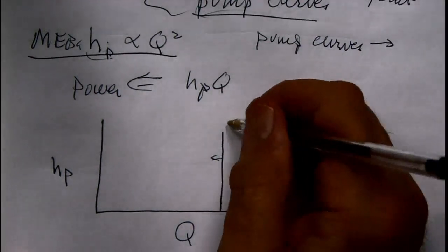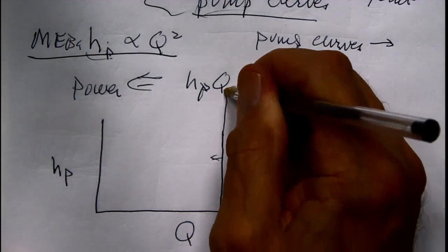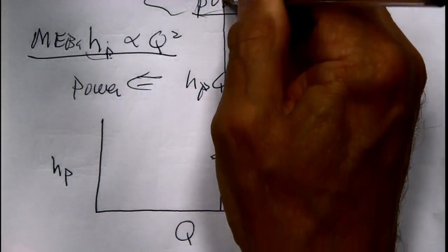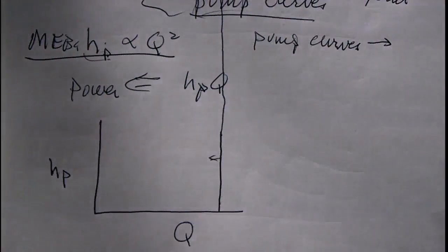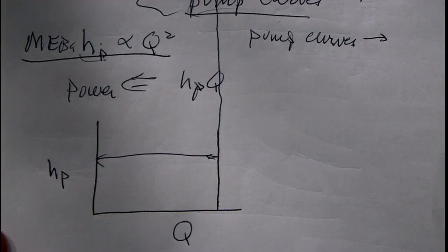Now with a positive displacement pump, it's dangerous because it just continues on and on. So you don't want a pipe rupture, and you don't want a blood vessel rupture on you. So oftentimes you want to have a relief valve sitting there.